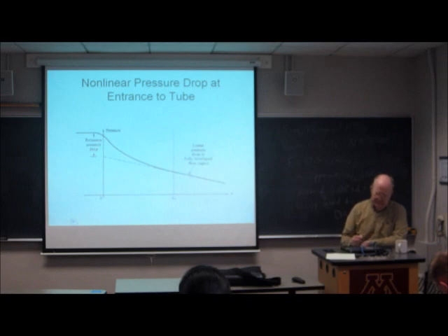This is another plot of the entrance length, and it shows how the pressure varies with distance until the laminar flow is fully developed, and then it becomes linear with distance. But during the onset of the laminar flow, it's a nonlinear distance dependence.